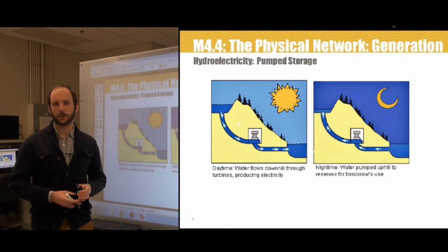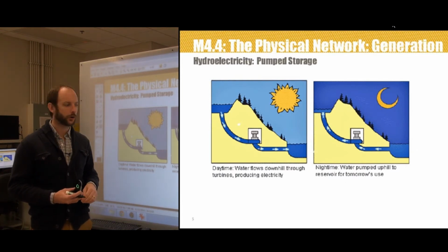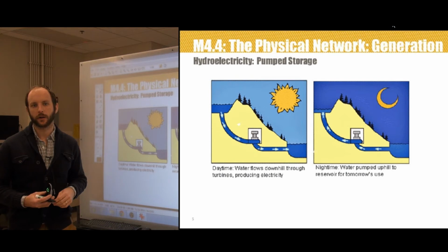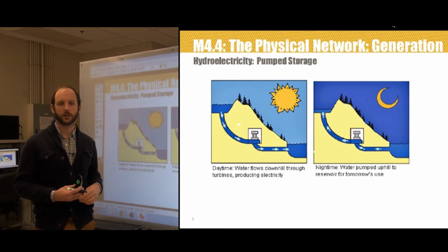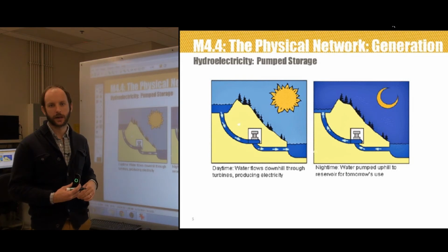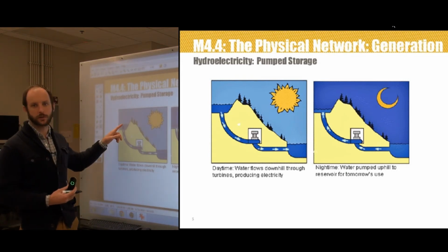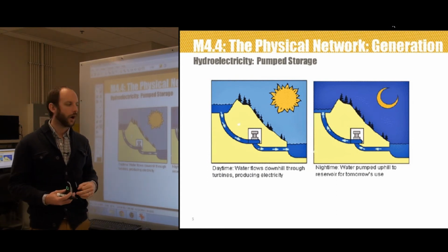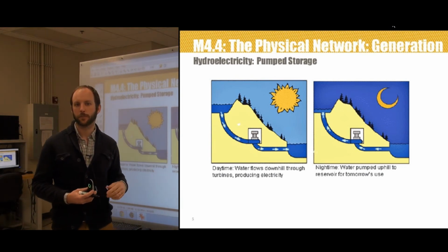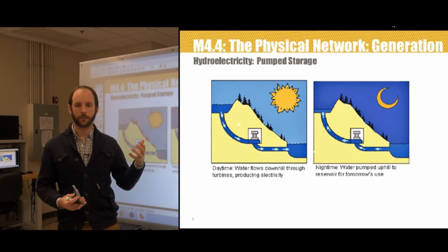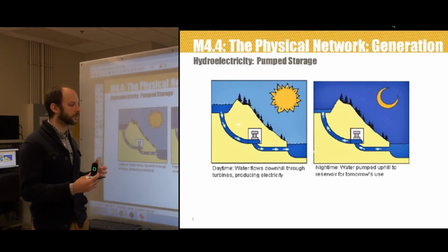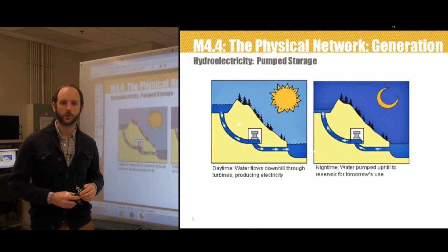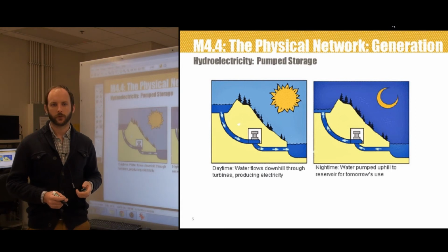Often hydraulic dams can be used as sources of energy storage. To do so, water in a lower reservoir is pumped upstream with pumps into a higher elevation reservoir at night or weekends using lower cost energy from thermal plants during off-peak hours. During peak load, water is released from the upper reservoir and it flows through the mechanisms that we just showed to generate electricity. Often this generator turbine assembly in these plants can be run either as a motor or as a pump, so you don't actually have to have both separate units there. You kind of combine the function into a single one, and this equipment can kind of do double duty. This technique is called pumped hydro storage.